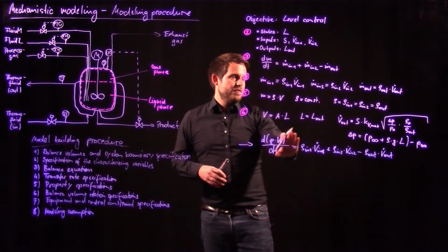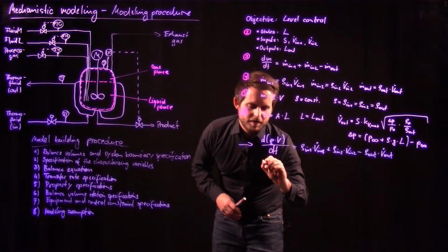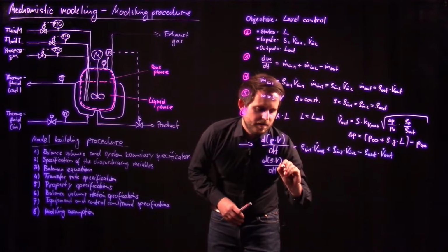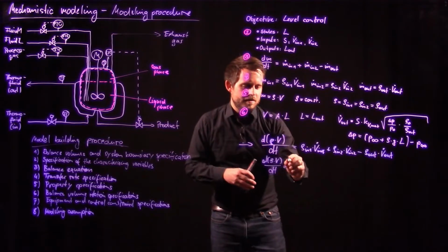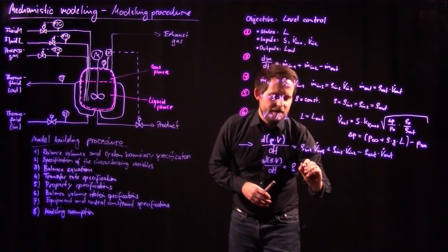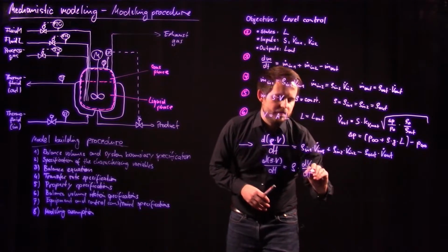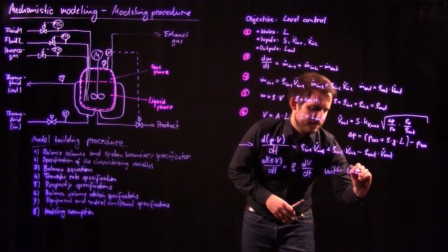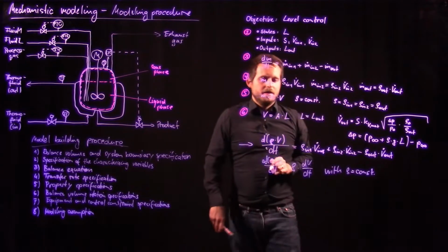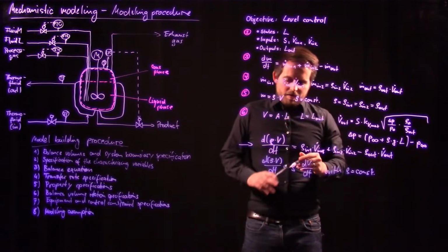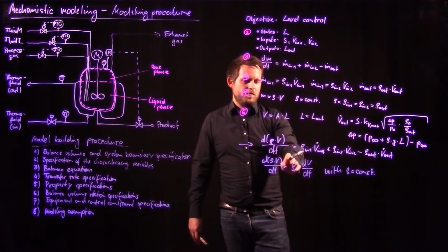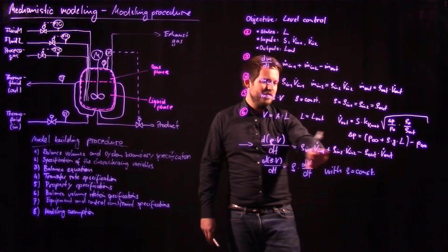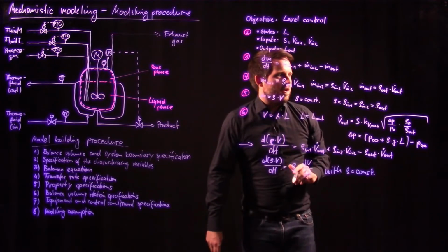the density was assumed to be constant. Therefore, the derivative with respect to time of the density times the volume is equal to the density times the derivative of the volume with respect to time. This is true with rho equals constant. Now, after that step, you could plug this into the equation, and you clearly see that since we said all the densities are equal, all of the densities diminish.